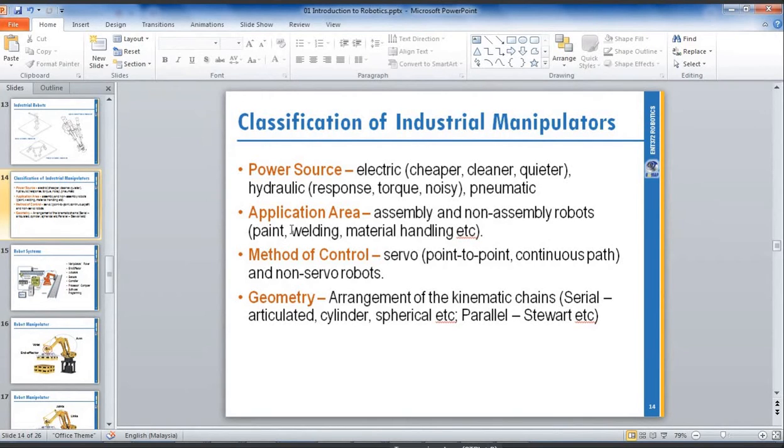So your robotic arm has good flexibility for tasks such as painting and welding. Painting normally needs to be very flexible, same as a human hand. So you need 6 degrees of freedom. One type of robot that has good flexibility is the articulated robot.